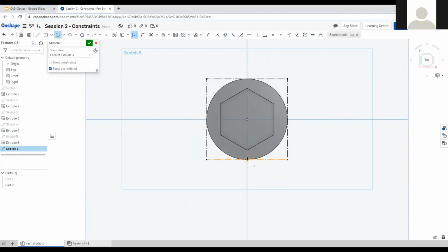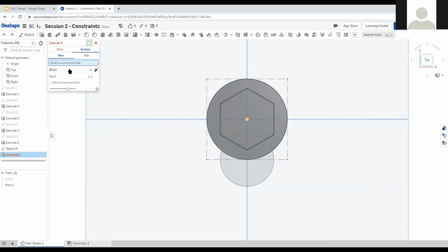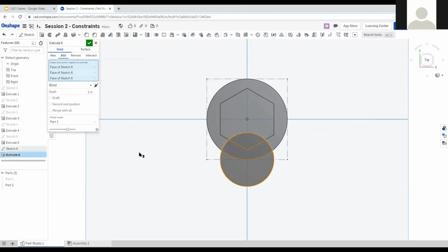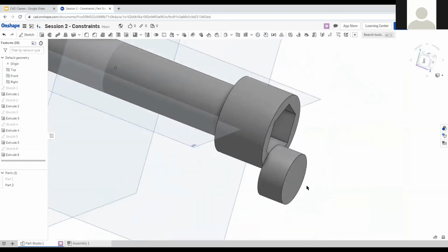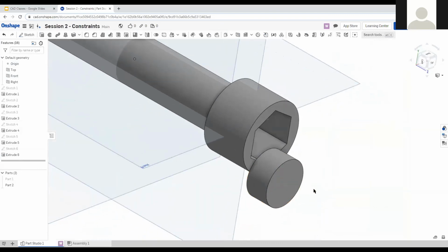We're going to create a wheel wherever we want that wheel to be. We don't want that wheel to be a construction line, and then we can just extrude that wheel out. A solid add. We're gonna go that area. That looks right. And then we want this to just go half an inch. I like half an inch. And that'll be merged with part two. So now we have added a very simple wheel on the side of our car.